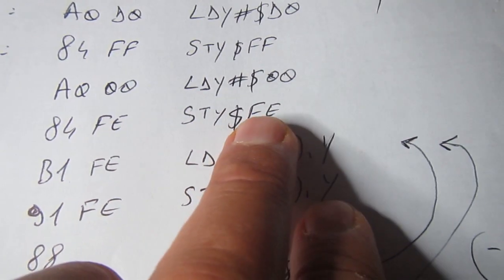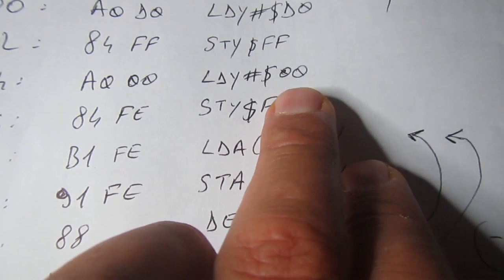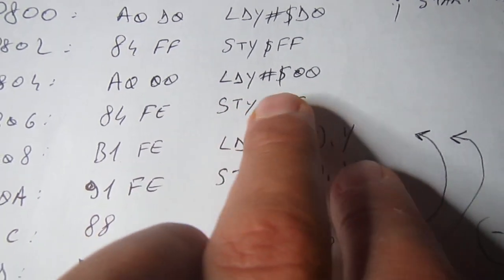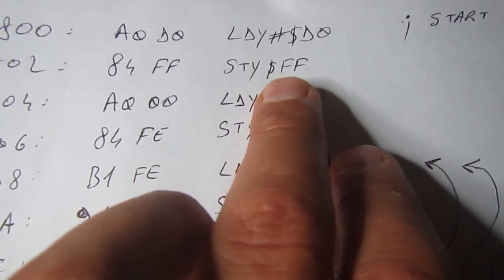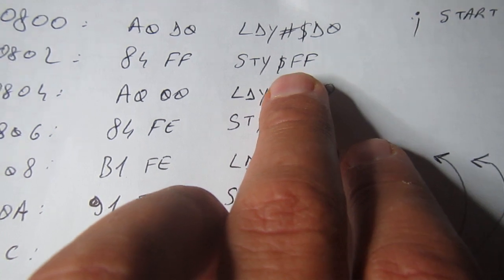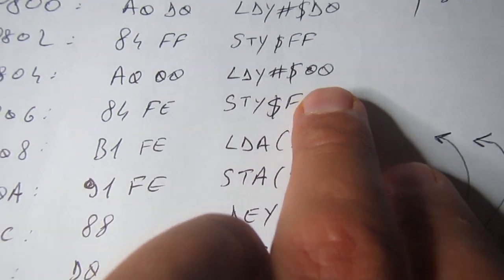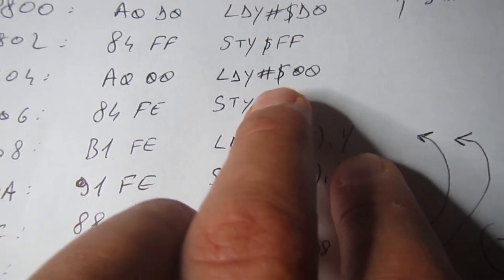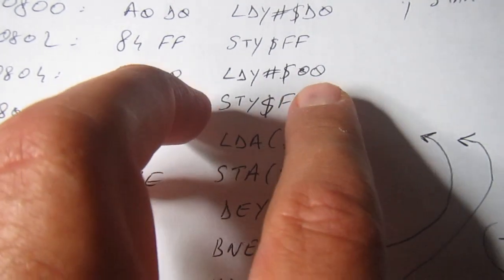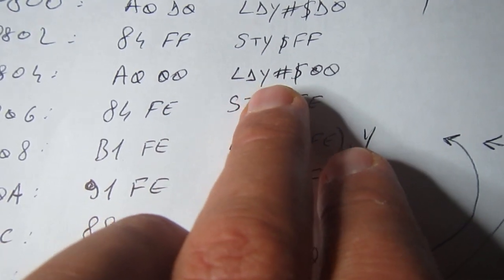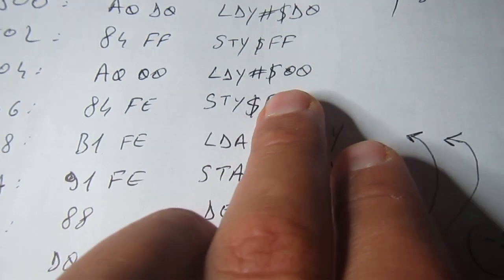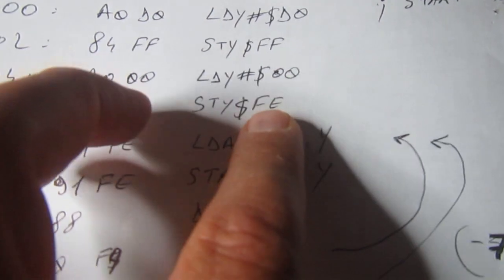So on the first byte we write 00. We load register Y, which is an 8-bit index register on the 6502. So I loaded the D0 first and stored it in FF of page 0. Loaded 00 and stored it in FE. Why I chose to load 00 after the D0 is because I will use register Y as an index, and it must start with 0. So I don't have to put 0 again if I first use 0 and then store D0.